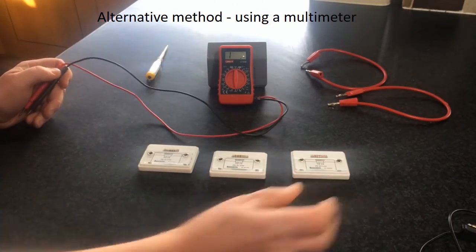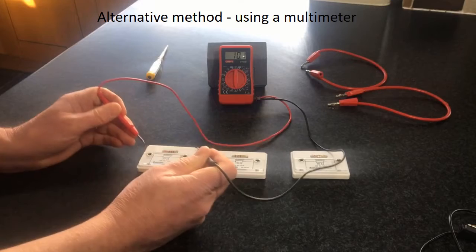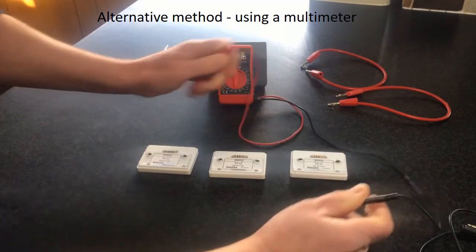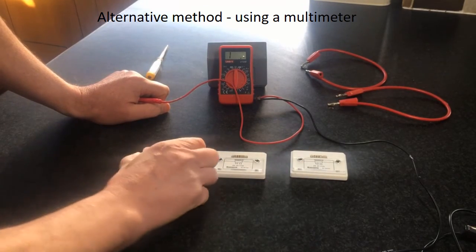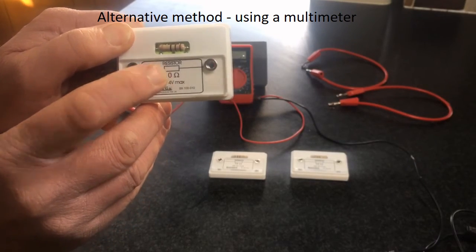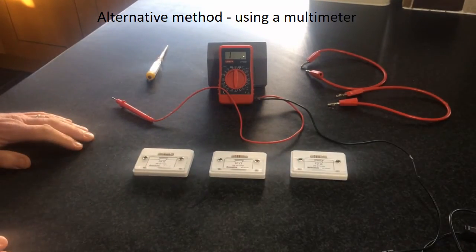So I'm going to start off just measuring the resistance of a resistor on its own. So I've got 10.2 ohms for that one, 10.2 ohms for that one, 10.1, 10.2 ohms for that one. So for the sake of simplicity, I'm going to say that it's 10.2. So you'll notice straight away that even though they're marked with 10 ohms on, in actual fact, that's only an approximation. So it's 10.2. So be a little bit careful with that, because you might find that it confuses you when you don't get the values that you're expecting. So we're going to say that they're all 10.2.